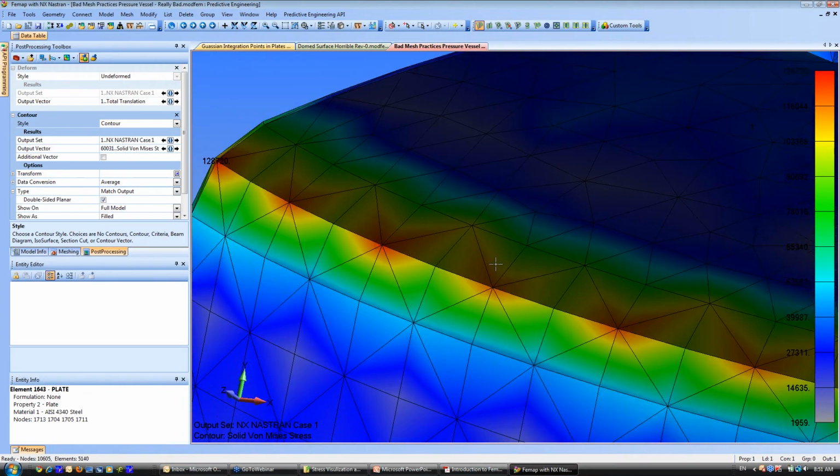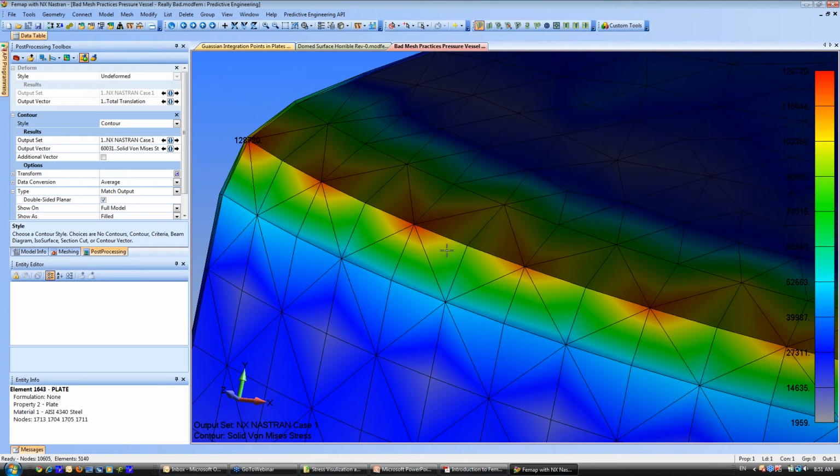And the reason why tets can be dangerous and sneaky is that you've got to remember the Gaussian integration points on those poor little elements. Just try to figure how in the heck you're going to get one by one by one normalization on an element like that. I mean, just think where the Gaussian integration points would be, about where it's calculating stresses and how it's doing things. And I have some more I want to add on to it, but you can just look at that. And now that you know how element stiffness terms are created, that it uses a normalized coordinate system and a Gaussian integration, you would look at this and go, how in the heck would it get one by one out of that?